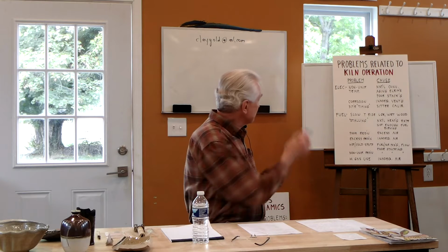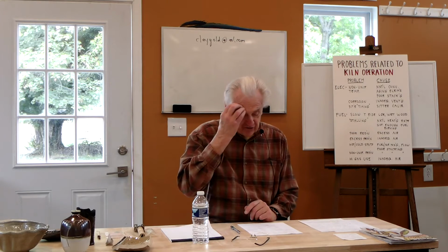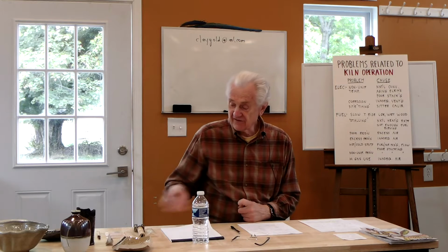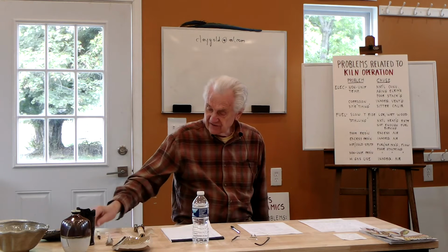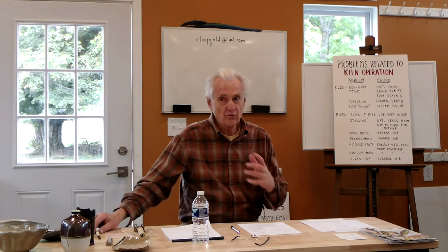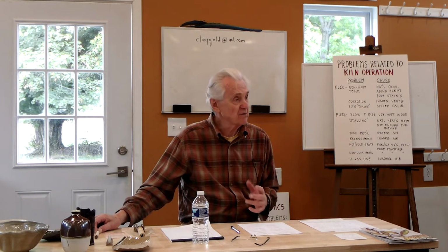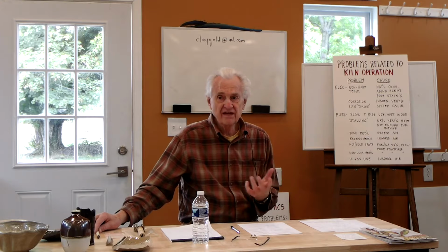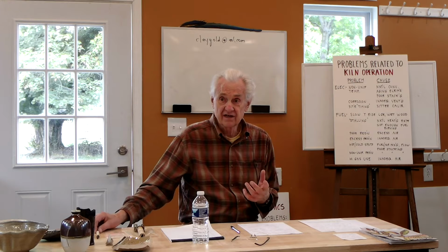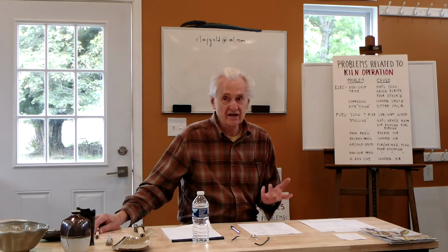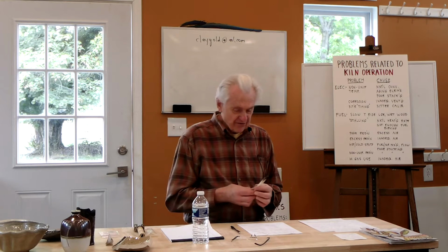Another common problem with electrical kilns is corrosion of the bricks and the metal. And this is actually due to the fumes given off from the clay and the glazes when they're fired. One of the main types of fume that comes off is sulfur oxides from impurities in the clay. And when they meet the air, they form sulfuric acid. This is the same kind of acid you have in your car battery. It's a really strong acid, and it eats all the metal parts, and it actually attacks the brick. I've got some examples here I can pass around.